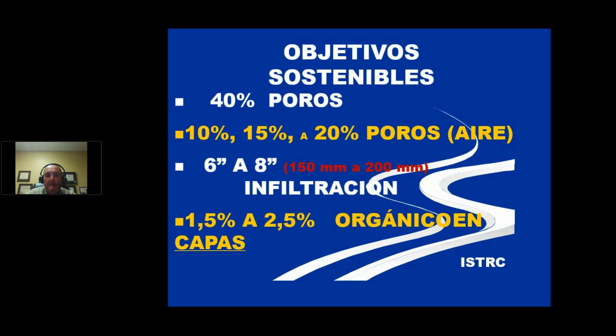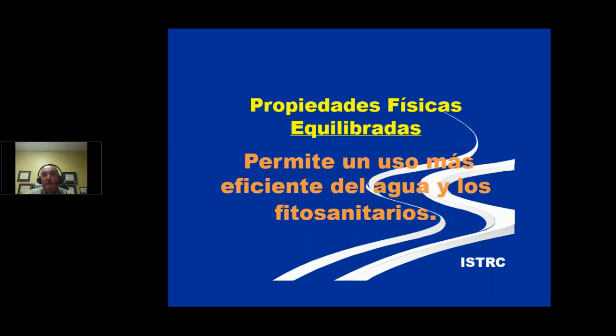So we're looking at infiltration rates of 6 to 8 inches an hour. That's a good range for a green that's in the open. If we have one that's got more shade and poor air, then I'd like to be in terms of 200 millimeters an hour and higher. I'm going to want to be more in the neighborhood of maybe 350 millimeters and higher, that type of thing. Okay. And so it becomes a matter of trying to balance the physical properties with our microclimate in order to help you grow high quality turf and maintain it for your golfing public.